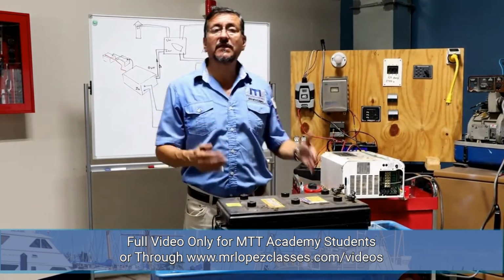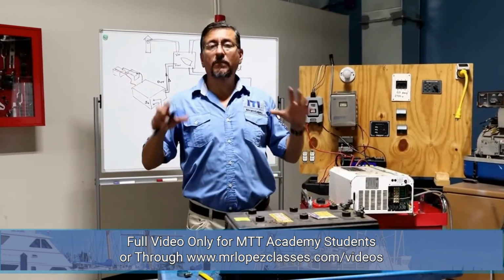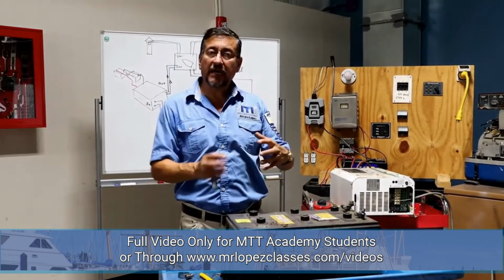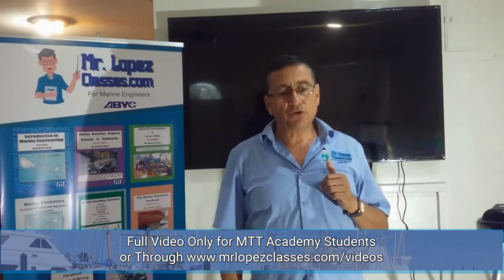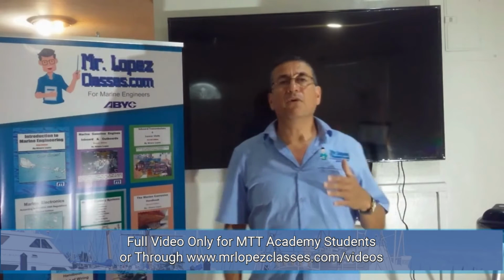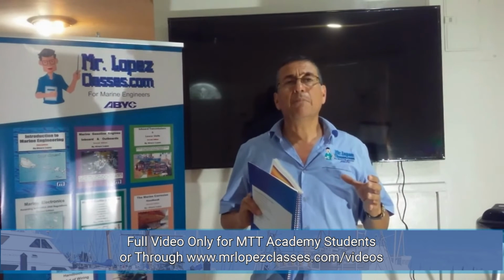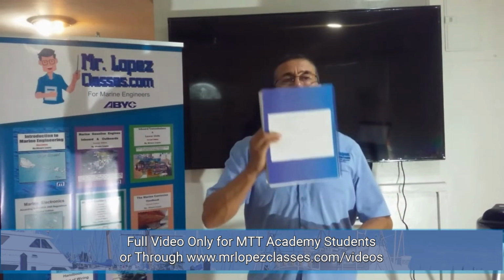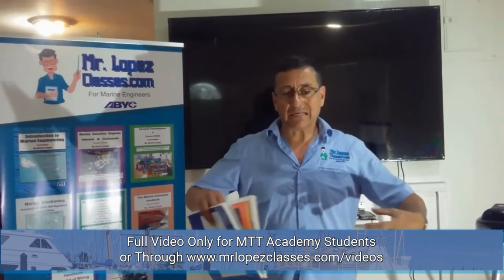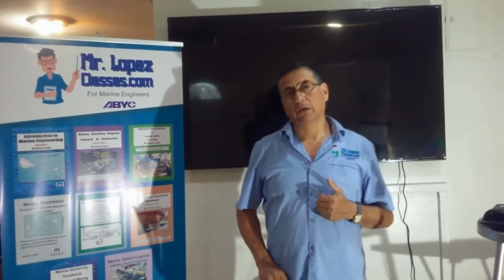The secret is to select the appropriate batteries in order to keep a good group of batteries properly installed, properly organized, in order to supply the amount of AC power required for the customer in the boat. Another important recommendation is to install the inverter separate, as close as possible to the battery bank, but not over the battery bank. It's logical because if you install the inverter over the battery bank, the gases, the fumes from the batteries affect the circuit boards on the inverter.